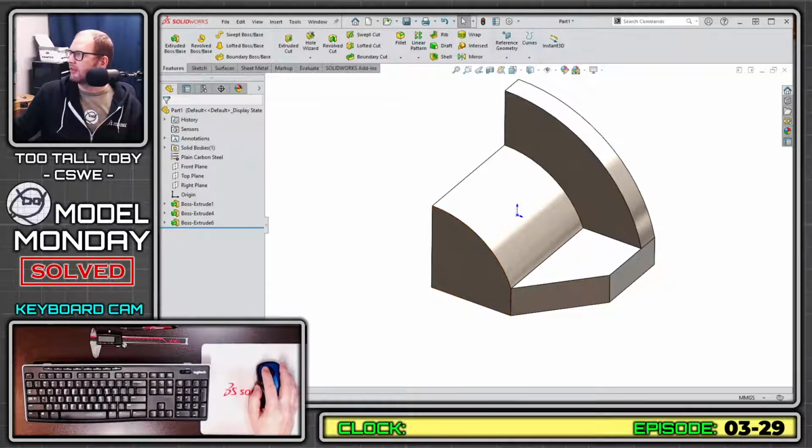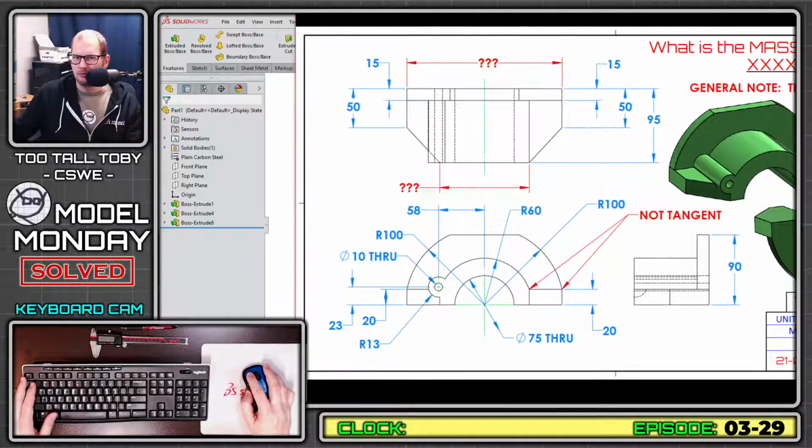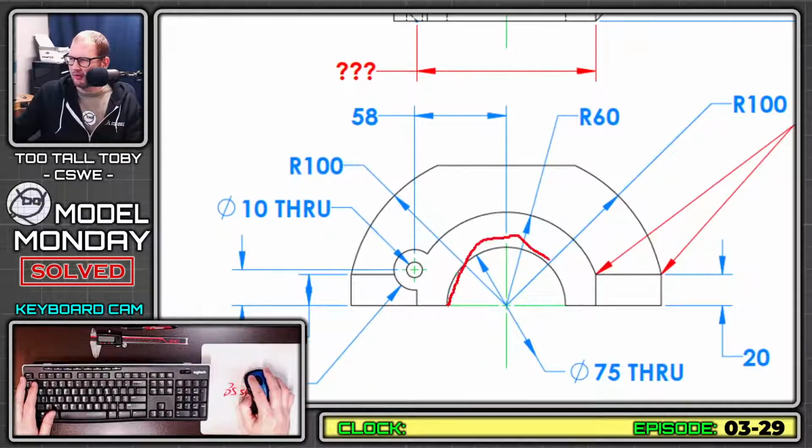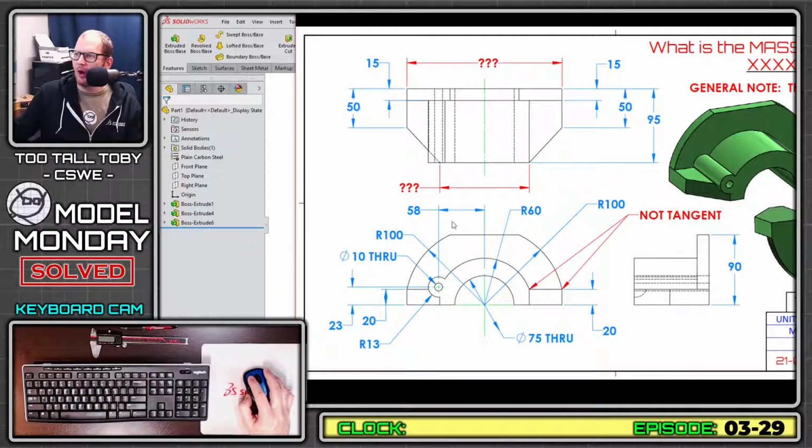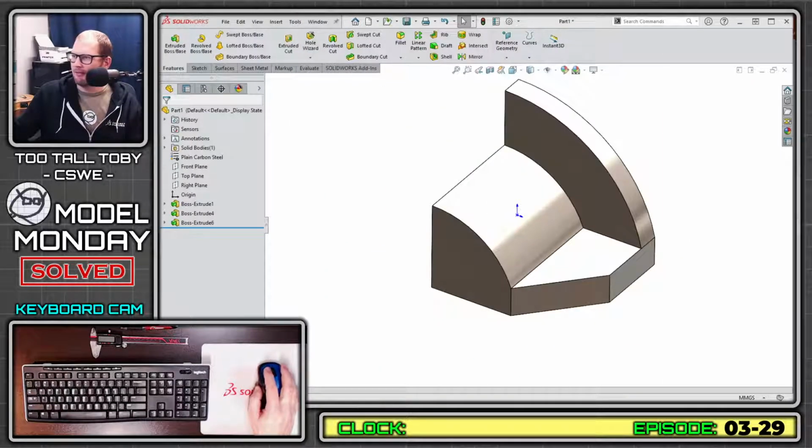And now for the final features, the cut extrude going down the middle and the asymmetric boss that's on this thing. So the cut extrude, you know, we would want to save this cut extrude for last. Usually you save your cut extrude for last. And then this boss over here. Well, this is probably the point where I would mirror it. Oh, I got to get my flat spot up top too. So that's 90 off the bottom to get that flat spot up top.